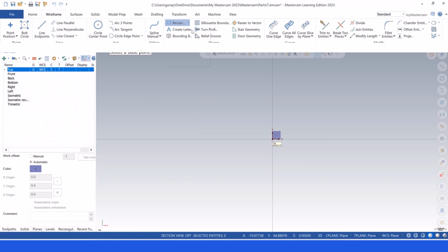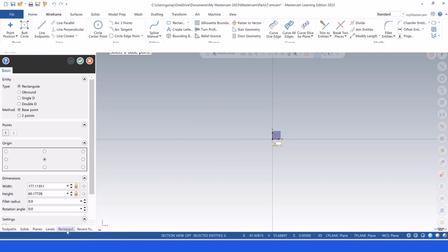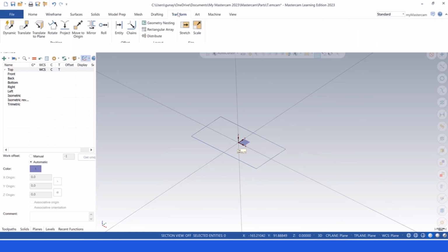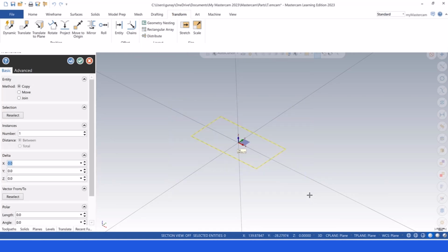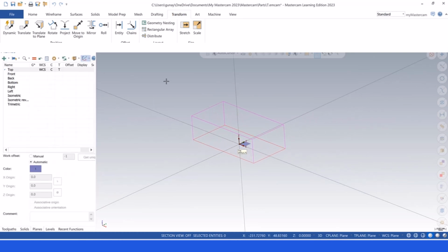And then let me create my rectangle shapes here. Okay, and this is the rectangle shape. It can be 150 millimeter, and then I'm gonna hit the origin position like this one. And after that, it's easy for us to use the transform and the translate options, and we can select our geometry, and then we're gonna use the 50 millimeter, or let me write 30 millimeter with join options to create that kind of shape. After that, we can use the right mouse button and clear color options.